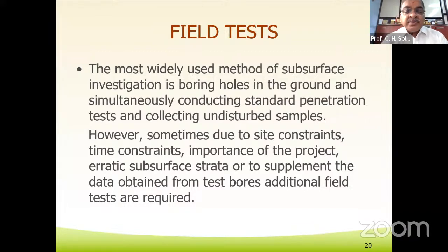The most widely used method of subsurface investigation is boring holes in the ground and simultaneously conducting the standard penetration test and collecting the undisturbed samples. However, sometimes due to site constraints, time constraints, importance of the project, erratic subsurface data, or to supplement the data obtained from the test bores, additional field tests are required.